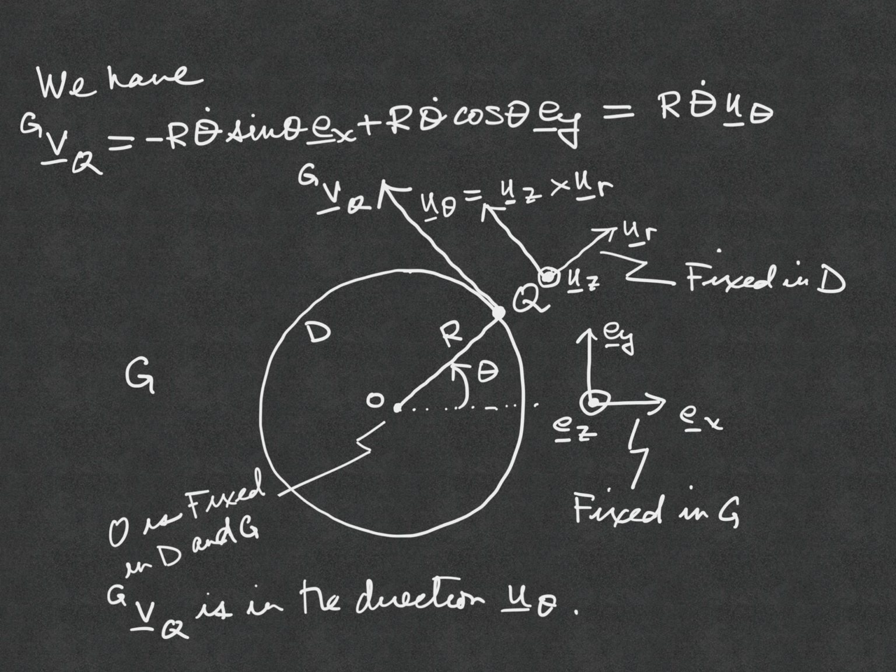And you can see that when you have to take this derivative again, if you use coordinates that are fixed in the ground, this is going to become an even more complicated expression because now you have a product that you have to deal with. It's theta dot sine theta, and you've got another product, theta dot cosine theta, and you have to take the derivative of that with respect to time. That's going to be a very difficult and very mistake-prone process. But we are going to actually compute the second derivative, again, using the transport theorem, and we'll do that now.